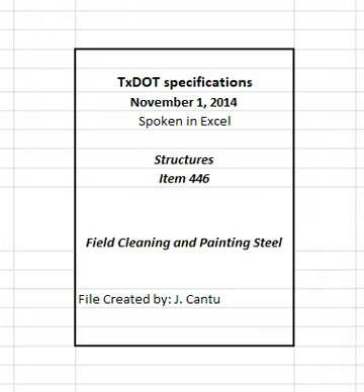Handle and dispose of non-hazardous waste as a special waste as defined in 30 TAC 330.2 or as directed. Provide documentation showing disposal of the waste was done in a suitable landfill holding permits to handle this type of material. Dispose of hazardous waste in compliance with applicable waste rules and regulations. Transport hazardous waste using a permitted transporter and dispose of in an authorized hazardous waste facility.